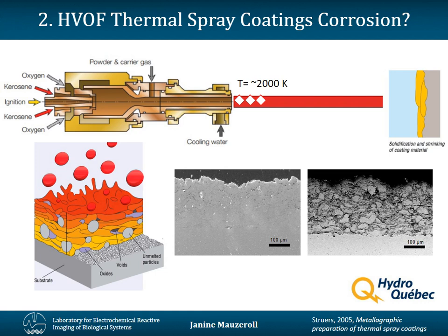This is when an industrial wants to protect an alloy further by forming a dense stainless steel, for example, film. In this case, you have an HVOF gun that combines oxygen and kerosene, and you introduce a powder carrier gas, which upon heating melts the particles and then forms really, really dense splats onto the surface that you're trying to protect.